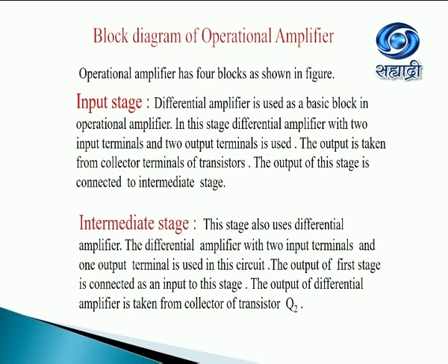This stage also uses differential amplifier. The differential amplifier with 2 input terminals and 1 output terminal is used in this circuit. The output of first stage is connected as an input to this stage. The output of differential amplifier is taken from collector of transistor Q2.